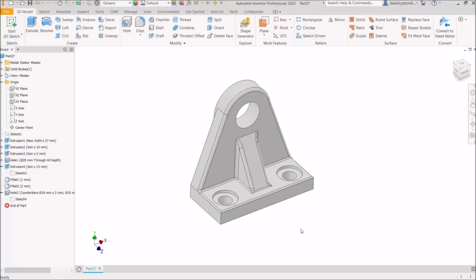And that's basically the real basics of how you create your first part in Inventor. So again, we will go and make sure our project file is set. We'll then choose our correct template to make sure we're drawing in the right part file. We then create a 2D sketch on one of the work planes. And again, I said I prefer the XY plane because that's the front face.